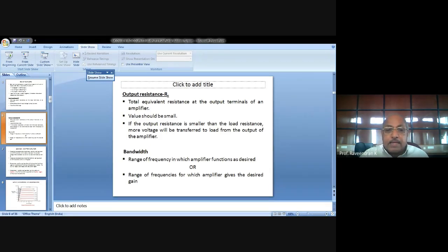So when you apply a sinusoidal voltage here, the DC conditions are already maintained on this transistor for operating in the active region, and along with that DC condition, you superimpose the voltage of the AC signal. Then what happens? When the alternating voltage travels on its positive half cycle, this positive voltage and the positive DC voltage are added together, so that the positive voltage across the base emitter junction is gradually increased. Isn't it? That is what is shown here.